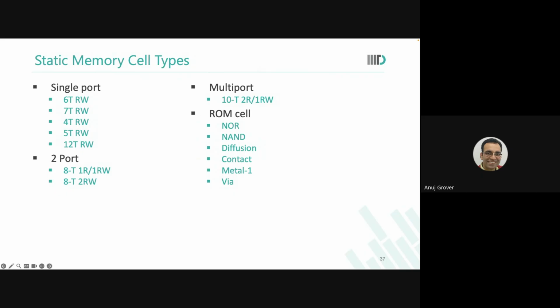So what you write from the processor side, the reading is happening from the bus side. So FIFO, whatever you write first goes out. You need two ports. You could have done with one read and one write port also. But here you have one read and one read-write port so that you can use it both ways.